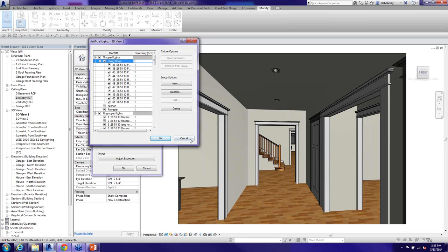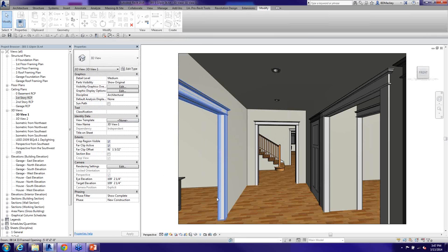So it's kind of one of the things I really do. Downside to that is you cannot group lights through a link, and you can't choose light groups that were created in a link. So if I'm on a commercial project and my MEP engineer went and put all the light fixtures in, Revit's going to use those for rendering, but I can't tell it which ones to use and not to use. So that's kind of one of the drag parts of the file.